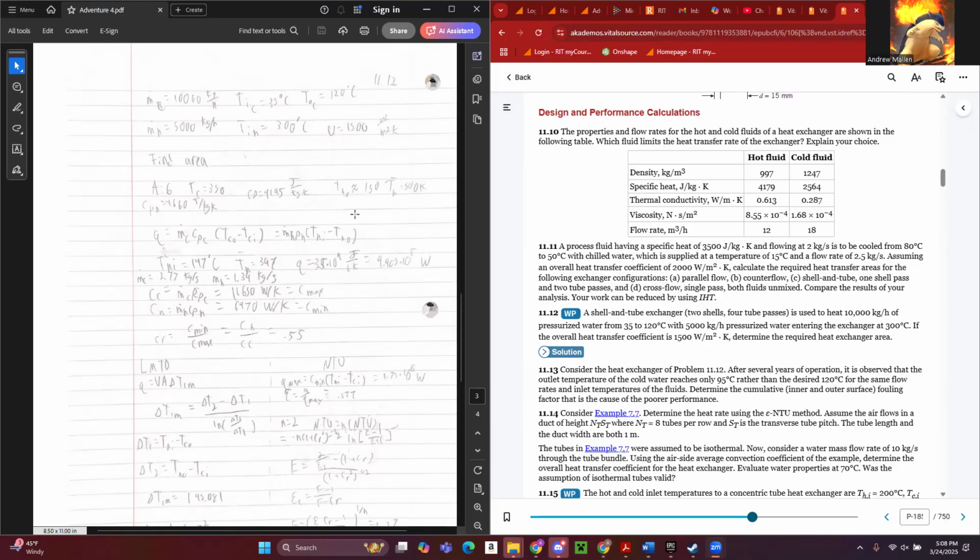In these cases, the best process, if you don't know one of the temperatures, is to just assume an outlet temperature, go through it, see what you actually get, and then if it's not super close to your assumed temperature, I'd say, arbitrarily, about 5 degrees off or something, then you just use that new temperature as the basis for the properties you use, and run through the balance again until you get an adequate temperature.